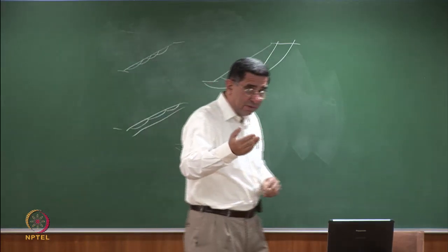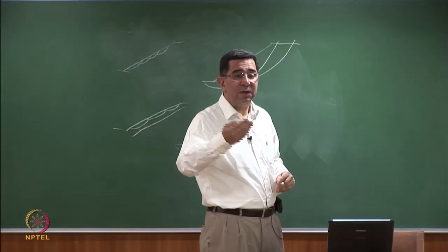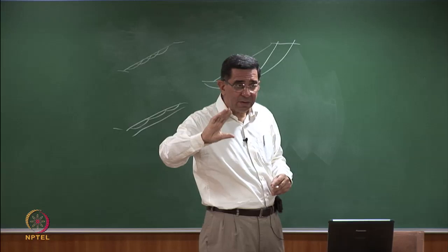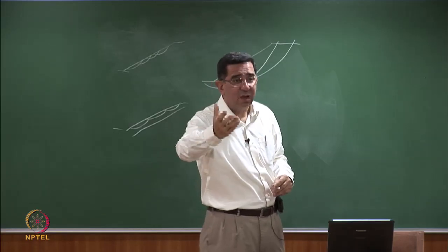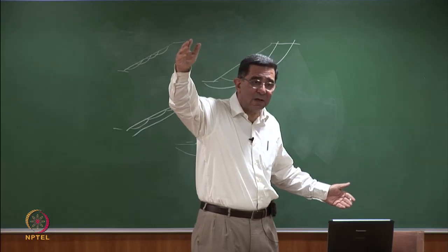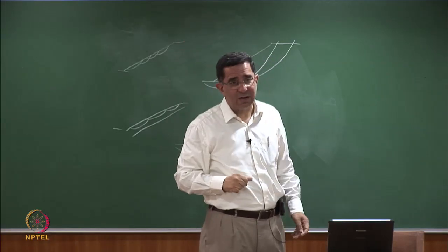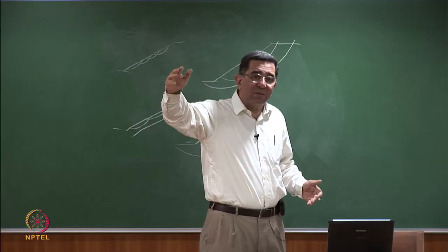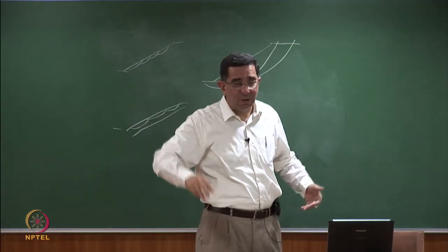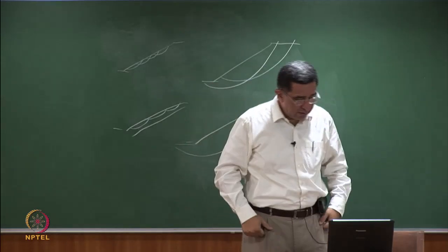So therefore, when you do landslide analysis, or when you are doing analysis of hill slopes where the rock is there at 2 or 3 meters depth, then the superficial failure surfaces are only 2 to 3 meters deep and the hill is 100 meters high. Then you have an infinite slope analysis. Whereas an earth dam of 100 meters high, which has no rock above or below, is going to be a finite slope analysis.